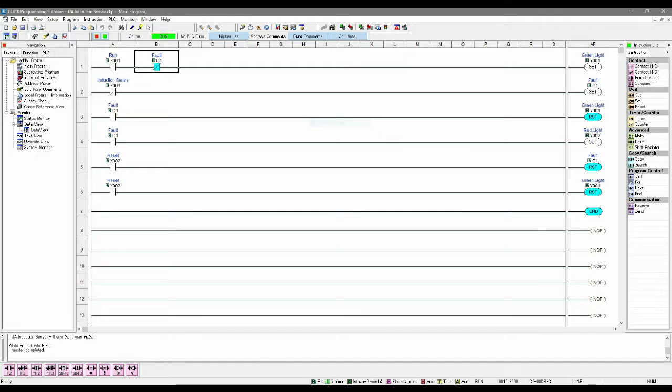Okay, this is a screenshot of our ladder logic program that we programmed into the PLC. You'll see our inputs labeled the X's and a C. As mentioned in the sketch before, the X's are our inputs, and those all hug the left side of the screen. On the right side of the screen, under column AF, are our outputs. Those also have different commands set with them. You can see some of them say set, reset, and end. The light blue indicates that that particular component is active.